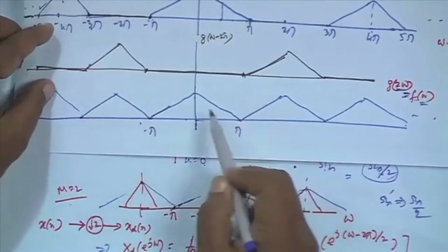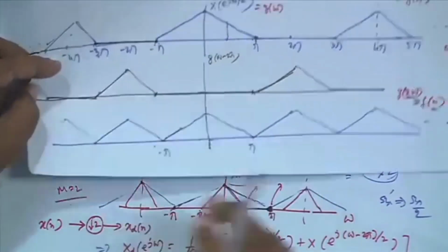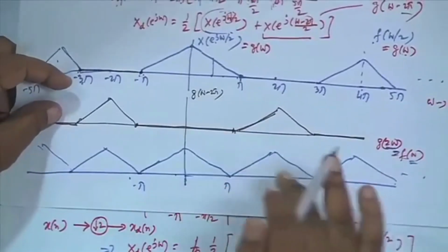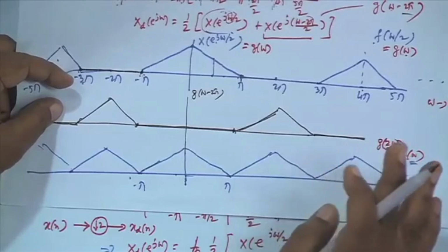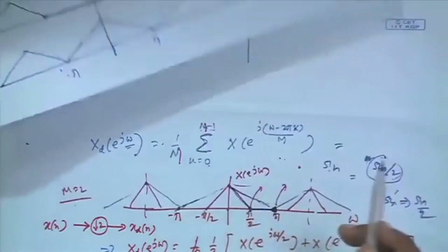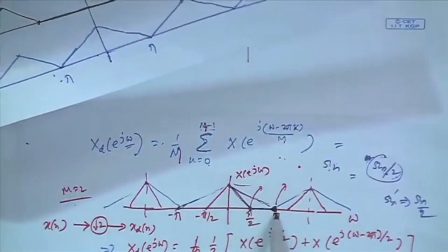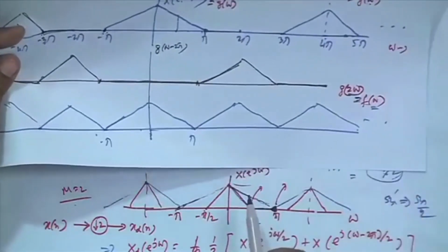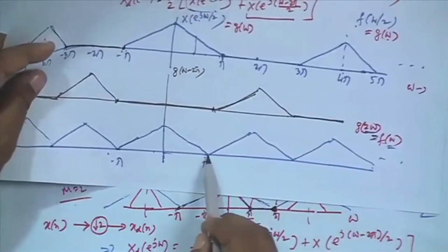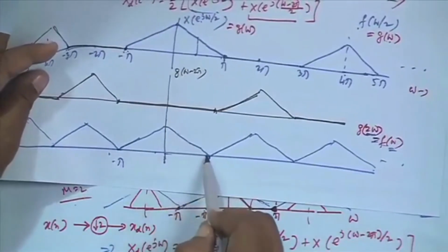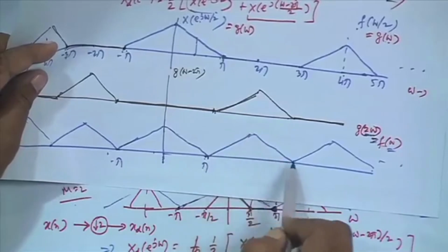Because half sampling frequency and band limiting frequency are not coinciding, I brought down the sampling frequency, and therefore half sampling frequency by a factor of 2. Earlier, half sampling frequency was twice the band limiting frequency, that is why it was pi by 2 so pi. Now, half sampling frequency is the same as band limiting frequency, but half sampling frequency always maps to pi, therefore band limiting frequency also will map to pi. That is why band limiting ends here and then a new block again starts like that.